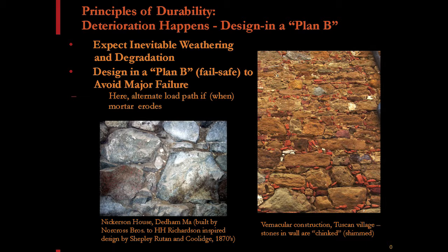So when you have large stones like this, if they left all this space in between as just mortar, then when that mortar erodes, everything starts to shift around, the stones move and shift, and walls start to get bulged and displaced and crumble and tumble out. And when this erodes, you've still got all this point-to-point contact to keep everything stable and in place, so it acts more like a dry-laid wall, and that way it becomes very easily reparable and maintainable and sustainable over time. Easy to keep that going.